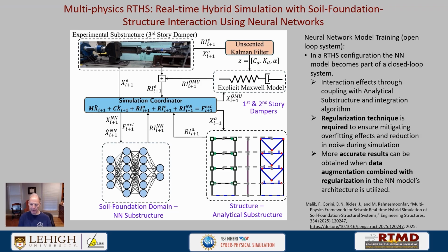That's where we augment the model assumptions of the damper. We do a wide range of parameters in order to try to bound the potential variation in the properties of those dampers. And that allows us to achieve, hopefully, more accurate results in the hybrid simulation when the properties of the damper, which are not well understood, appear in the problem.